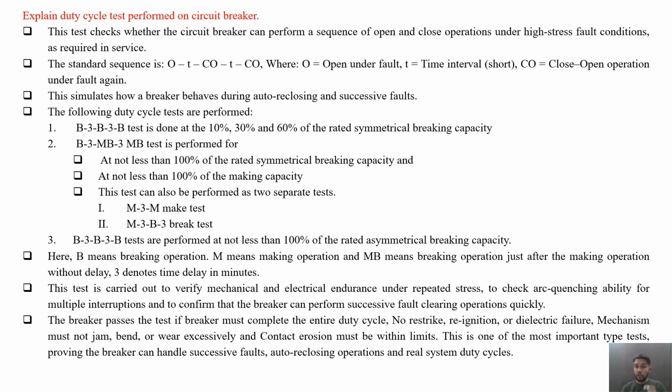O-t-CO-t-CO, where O means open under fault, t is the time interval, that is a short duration, CO means closing operation followed by the opening operation under the fault again, and then again t is the time interval which is longer than the previous one, and CO, that is the closing operation followed by the opening operation. This simulates how a breaker behaves during auto reclosing and successive faults.